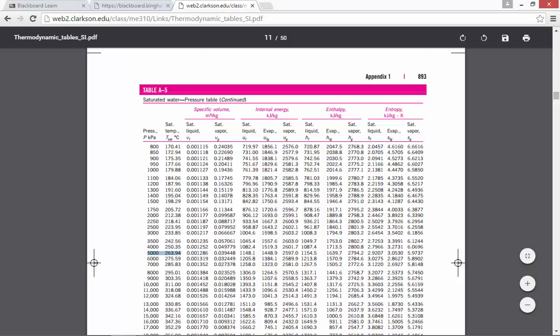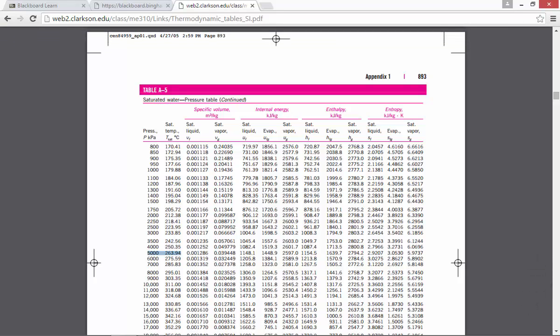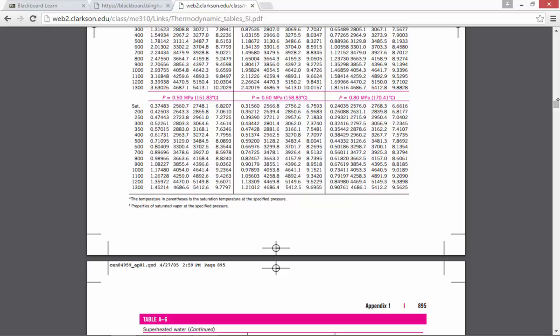Well, that's enough. So the saturated temperature, which would be the temperature in the phase change process, is 263. But the steam at the inlet is at 650 degrees C, which clearly says that it's superheated because the temperature is much larger, much warmer than the saturated temperature. So on the graph, we have passed the saturated line and we've gone up to higher pressures and higher temperatures. So I need to go to the tables about